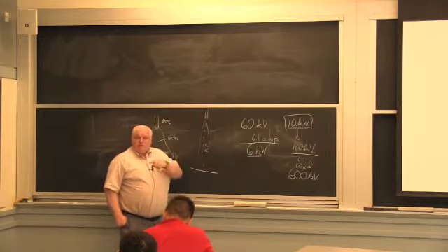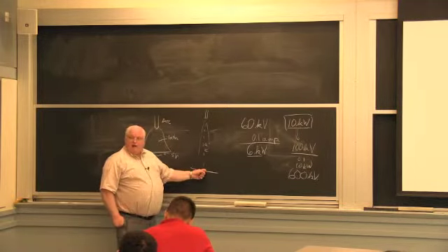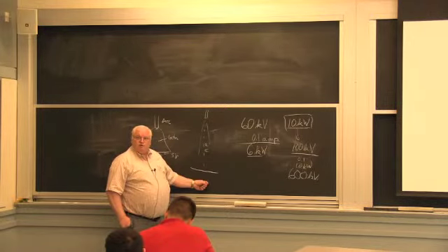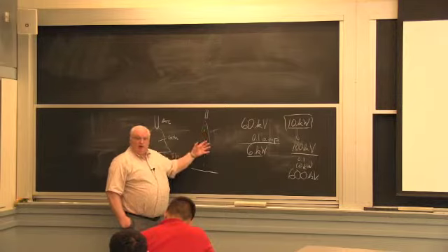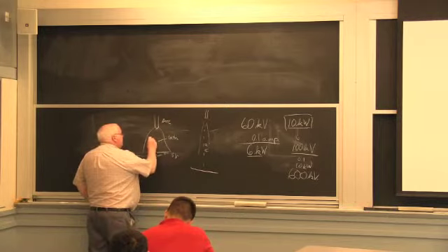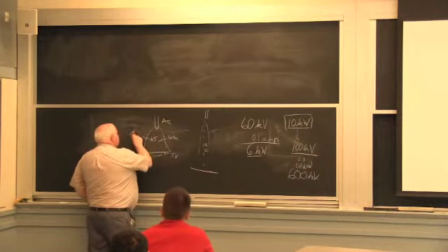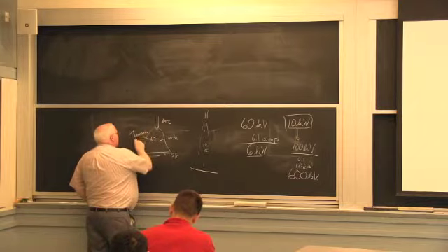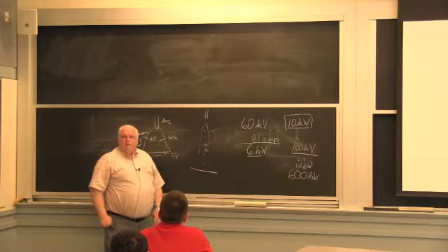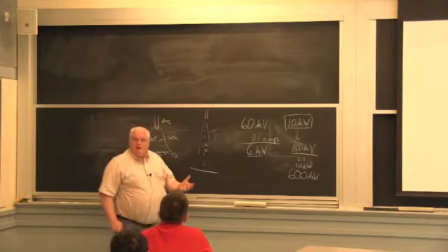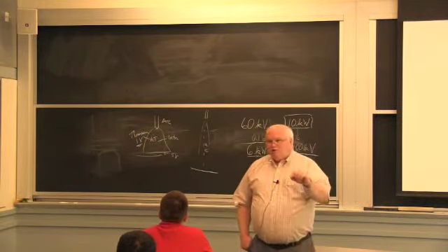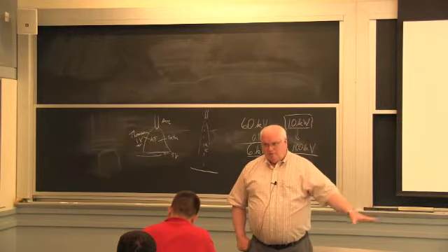So it's still electron flow heating, but you don't have an anode voltage drop because you don't have a gas boundary layer, but you do have the work function voltage, okay, and the kinetic energy of the electrons. Mostly it's the kinetic energy of the electrons. The kinetic energy of the electrons up here, the KT Thomson energy, was 1 volt. Here it's 60,000 volts or 100,000 volts. Very different electrons in terms of their kinetic energy. Each electron here in electron beam welding has enough energy to partially penetrate the surface. I'm going to go through that in a little bit, okay?